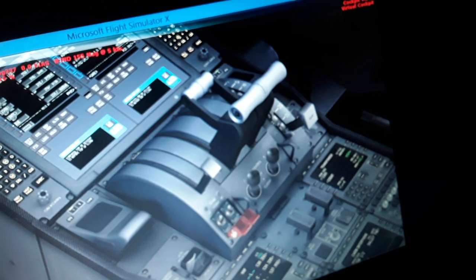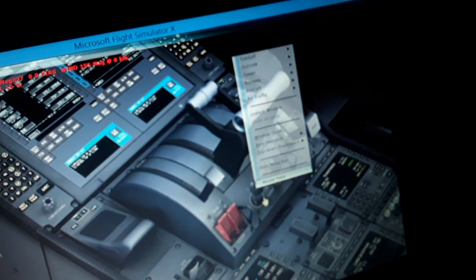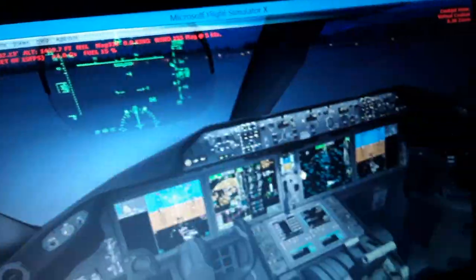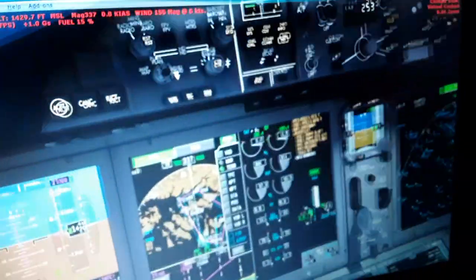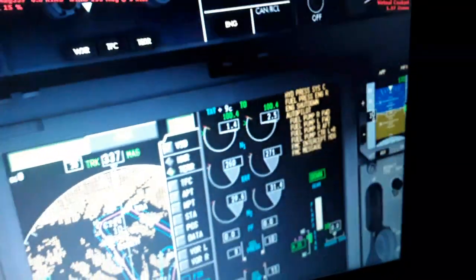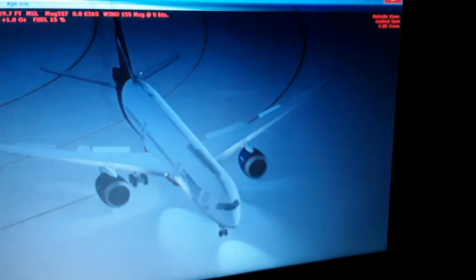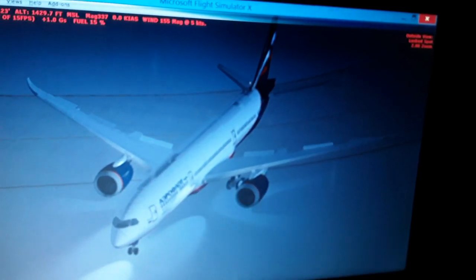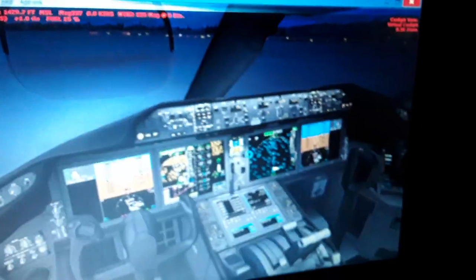So we're gonna use the outflow valves over here, off. Those off, you will see the engines are off. Some systems are popping up with yellow, with amber color. So we have the right and the left engine over here slowing down, so we need to start the engines very quickly over here. Go in the overhead engine, auto start both left and right engine.